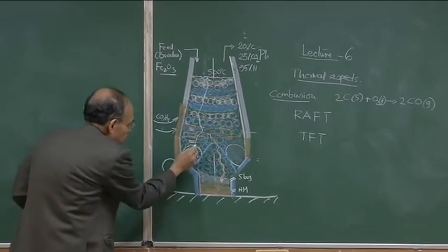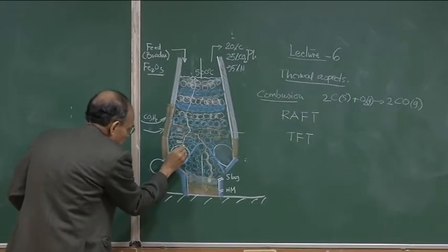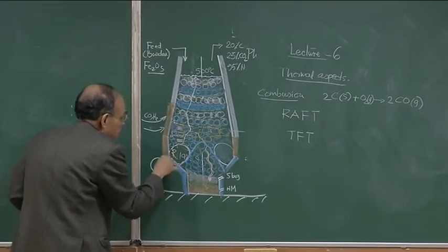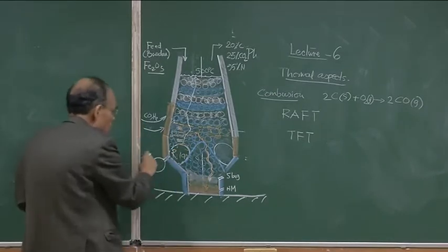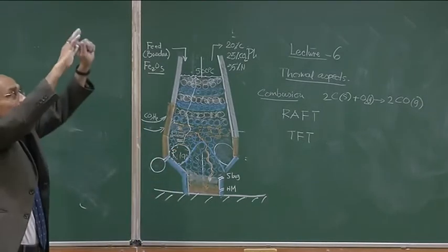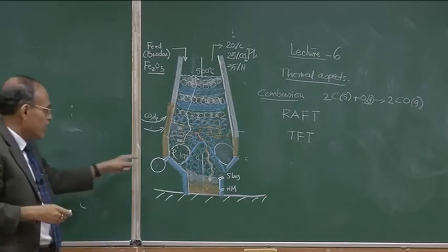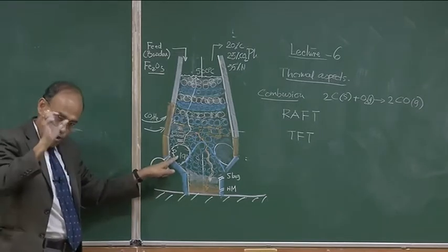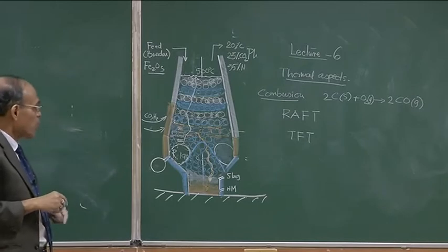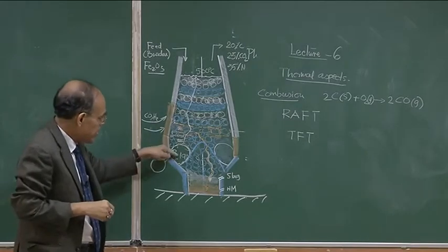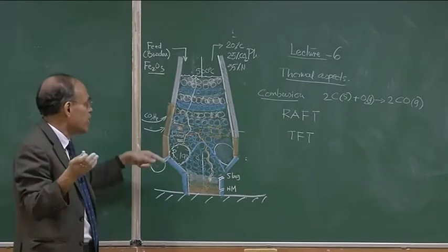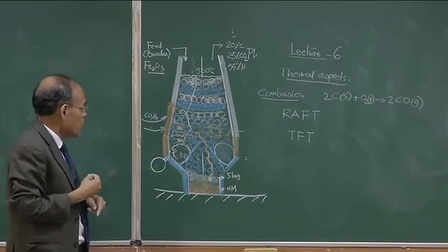you get a geometry. So, the moment the coke particle tries to enter here, it gets oxidized into carbon monoxide, and then you get this sort of geometry. It is a hollow region in front of the tuyere, and one can actually see it from outside through the window which modern blast furnaces are equipped with. The coke enters here, but vanishes momentarily, converting into carbon monoxide.